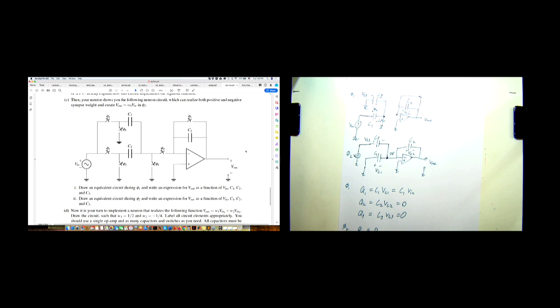Yes. Charge sharing is only applied at floating nodes, so nodes that are not connected to any sources or ground. The floating node becomes floating on phase 2 because you have charged it to some potential, dumped some charge on it, and then you open the bridge, as we say.